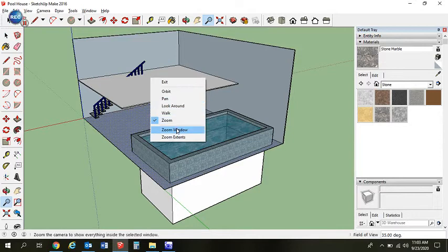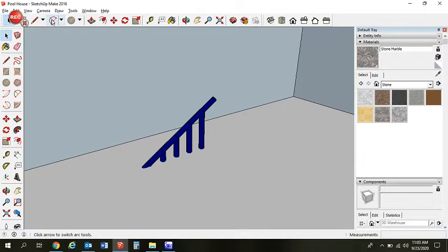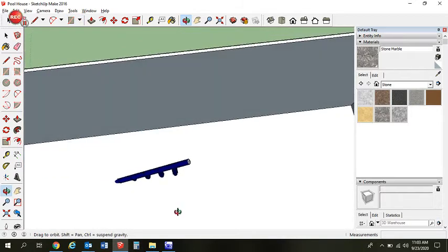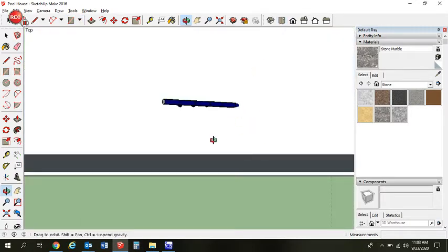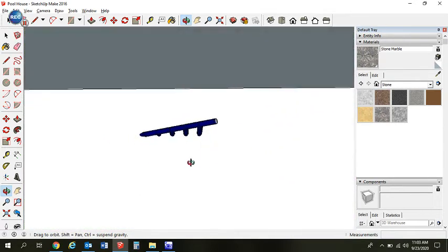Well, you don't want to run into the bottom of a floor, so we're going to now make a hole for the steps. And this one takes a little bit of guesswork, unless you did some other things before. Now I can see right there is the top step, so I'm going to just orbit where I can see that. I could also go to my top view here. It's a little bit off. And I'm going to get my rectangle tool again, and I'm just going to draw a rectangle from here and across, and let's try that.